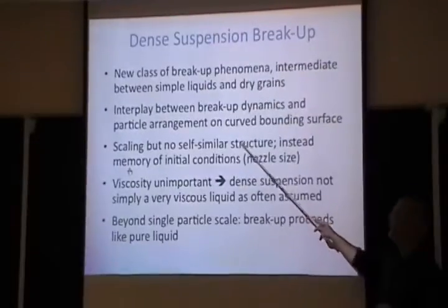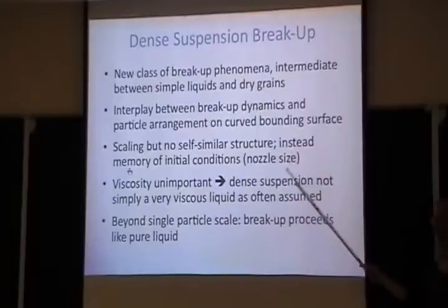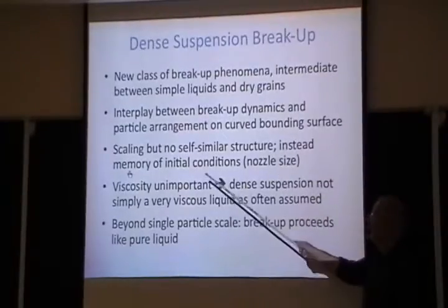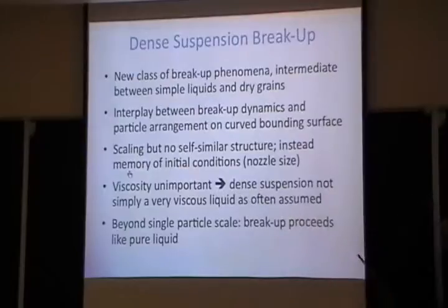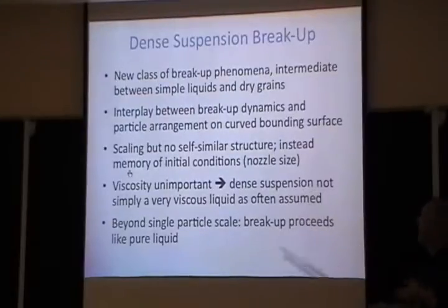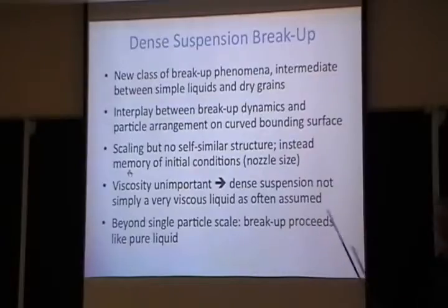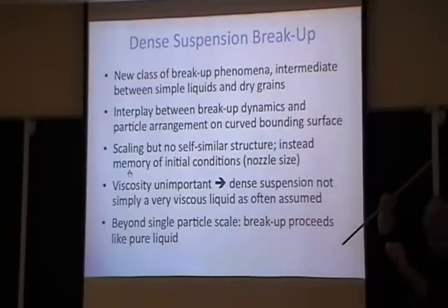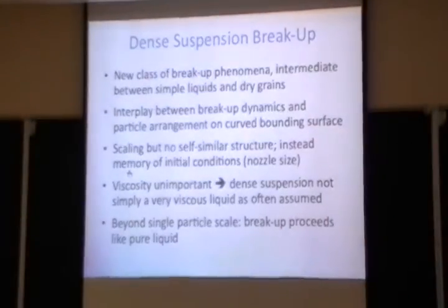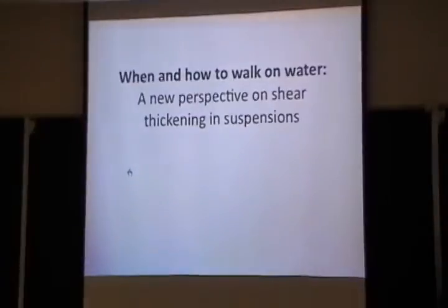What comes out of this is something that's not self-similar, so it remembers the particular nozzle size, but it has some scaling where the viscosity is not important. And that is different from what's usually assumed. Maybe for many applications that could be just fine, but not for breakup itself. And the one thing to remember is that eventually there are two particles held by a little liquid thread, and once that goes, then it's just liquid breakup. All right, so good.